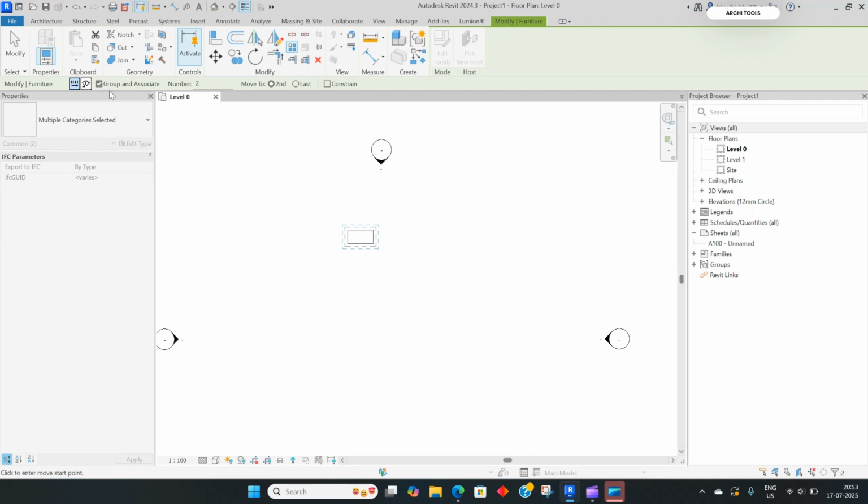If this is ticked, the objects which are arrayed are in singular array groups. This will be helpful for making array parameters in future whenever we want. And in other sense, if you want to keep it simple, just untick it.